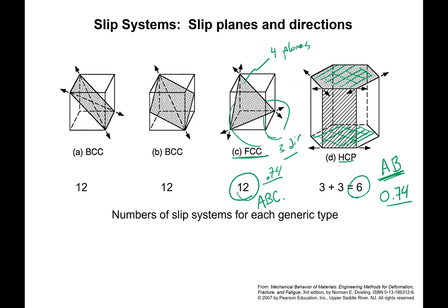And so the hexagonal close pack system will behave in a brittle way because we're limited in the movement of dislocations, right? And they're responsible for the ductile behavior, where the face-centered cubics are fairly ductile. All right, if you're reading in your text, the other thing that you'll see is that your text mentions that because the face-centered is 12 systems and the hexagonal 6, the face-centered is more ductile.